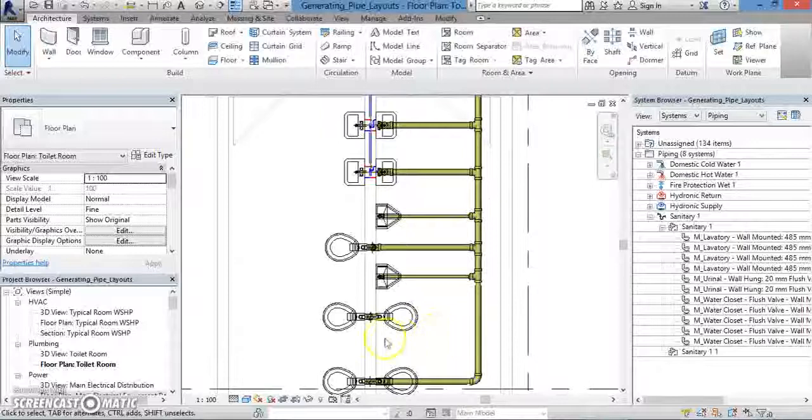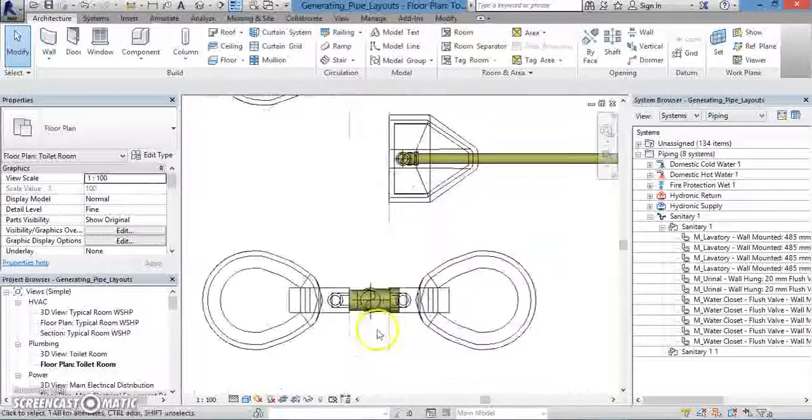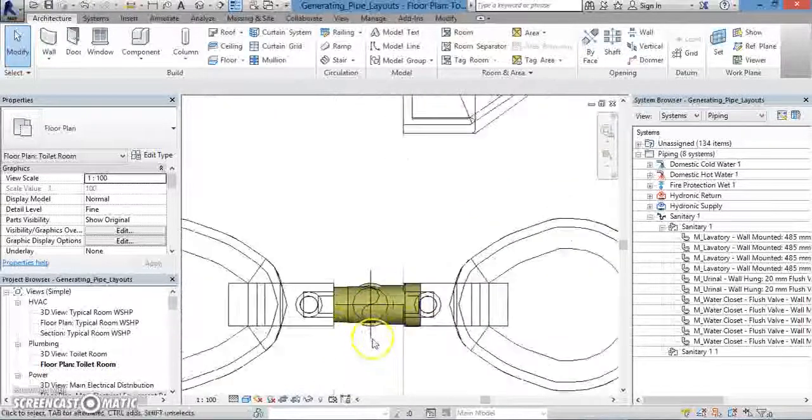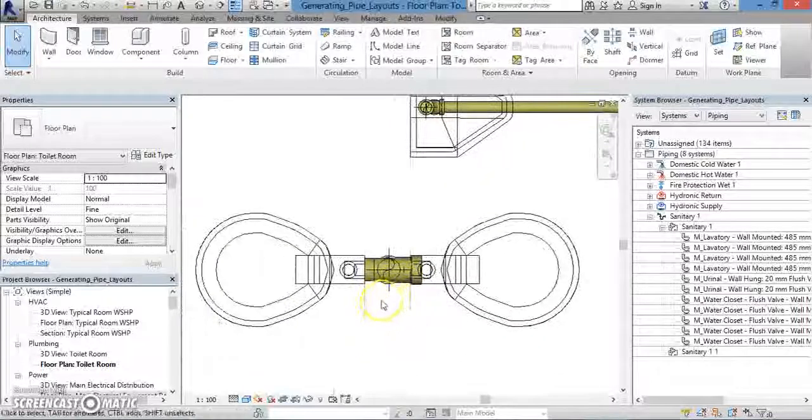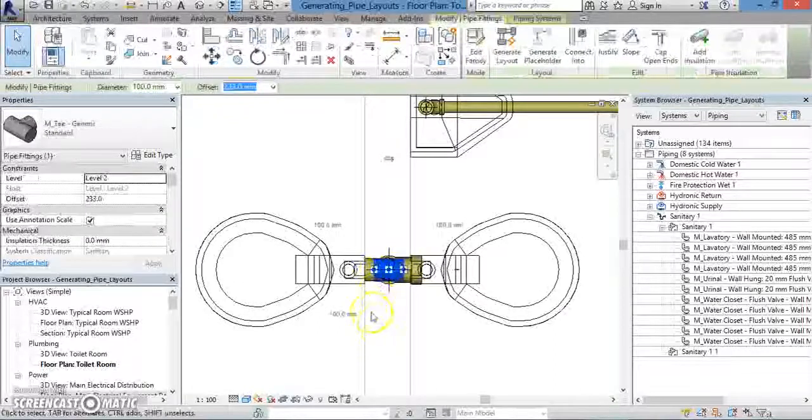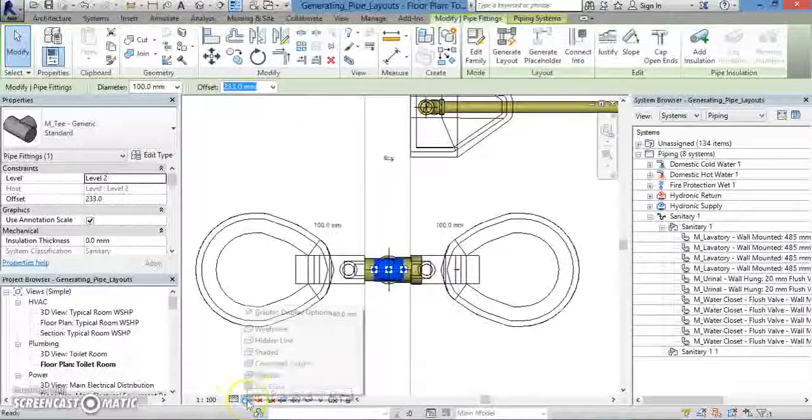So go ahead and zoom in on the connector between your 2 plumbing fixtures. Once you're in close enough to see it, left-click on the connector. For this project, because of the work we're going to be doing on it, we would recommend that you go down to the display toolbar directly under the viewing pane and change your display format to wireframe. This will let you get a better look at the details that you're going to have to work with.